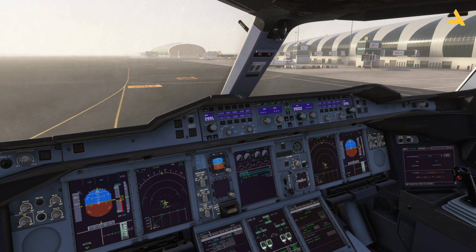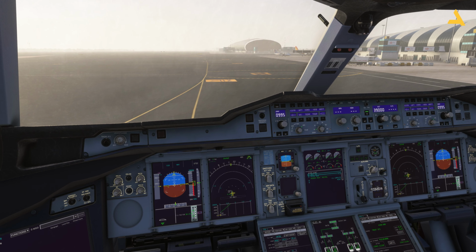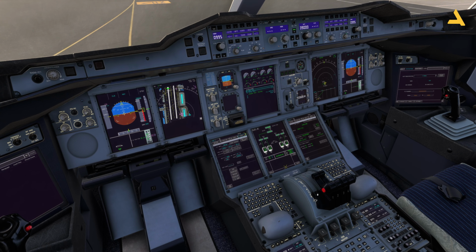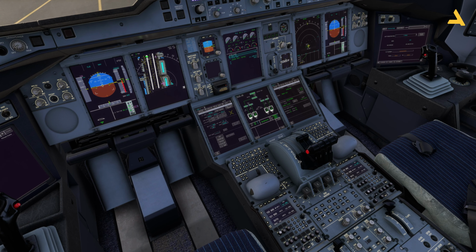That's it. Now in this plane, you can move this knob all the way to the left to get this airport chart to see the runway for the takeoff plus the taxiways. So I will just keep it like this. That's it. Now anti-ice is not required as I'm not flying in icing conditions. It's summer, and pitch trim is set and checklist complete.